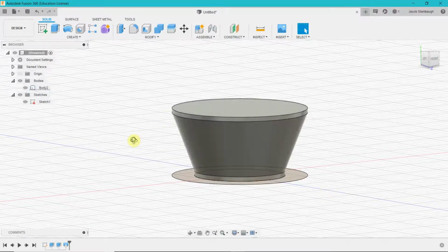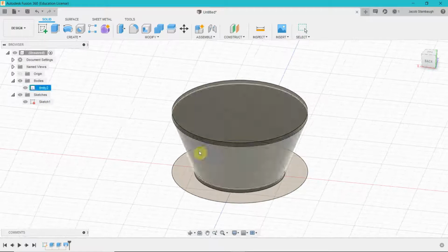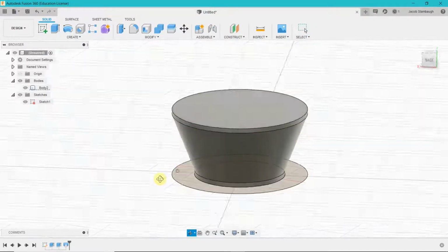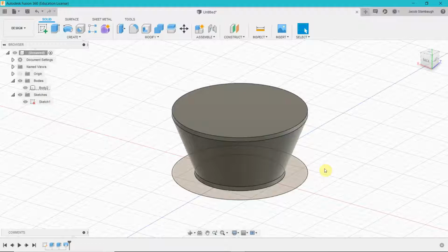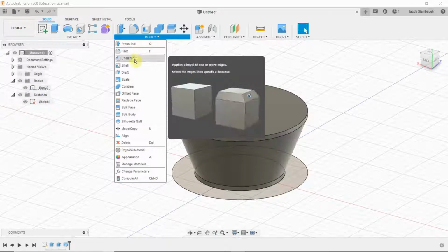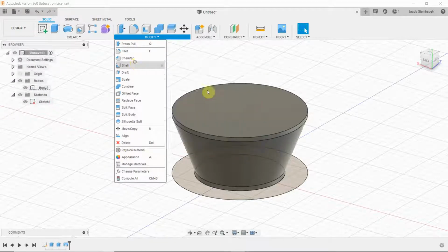This is completely normal, and this is a really good tutorial also on how to see what's wrong and edit what you want to make it seem more realistic. And so in our case right now, first of all, this plate is just, it's whack. So the first thing we're going to do is hollow it out using the shell feature.